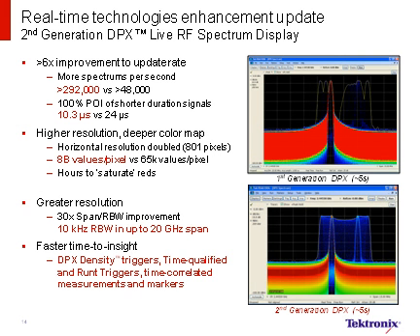These enhancements in our second generation DPX can be summarized as follows. A 6x improvement in the processing rate of DPX, going now to 292,000 spectrum updates per second, orders of magnitude faster than any spectrum analyzer available on the market. With this comes an improved probability of intercept for short duration signals down to 10.3 microseconds, 100% certainty. 8 billion values of pixel memory are now available to give a softer color grading and more detail contrast of infrequently occurring signals, as well as a higher resolution.